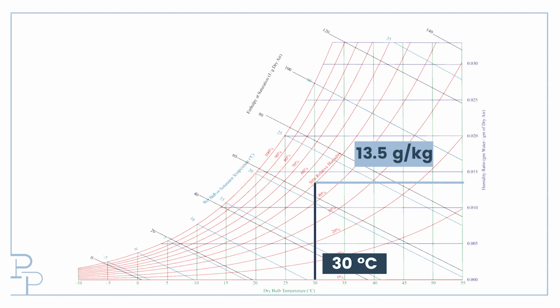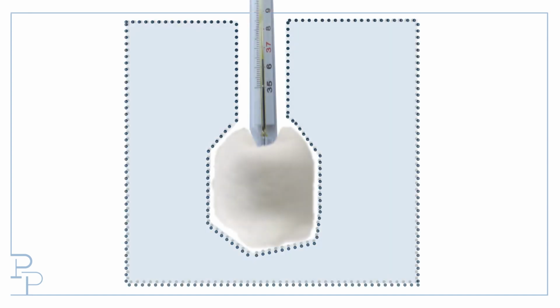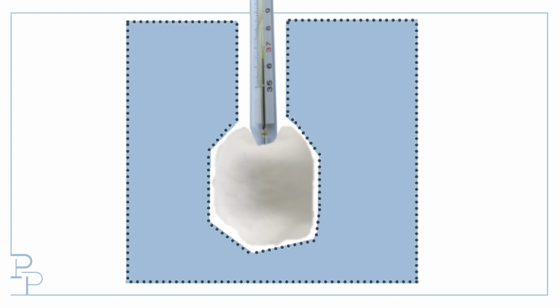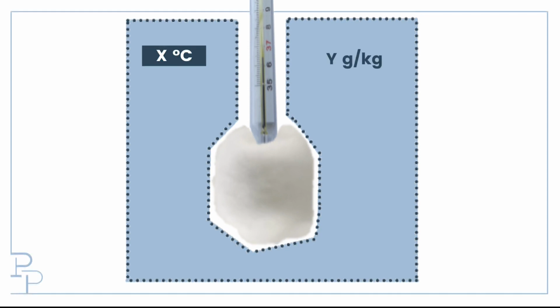Let's consider what happens when we're doing this wet bulb temperature measurement. Let's define our system as the air around the thermometer bulb around a wet wick. To start off, the air has some temperature and some amount of water. The air cools down when we measure the wet bulb temperature. Its temperature is dropping because it is losing energy. Where does that energy go? It goes into evaporating the water contained by the wick. The heat of vaporization of water is removing energy from the air.